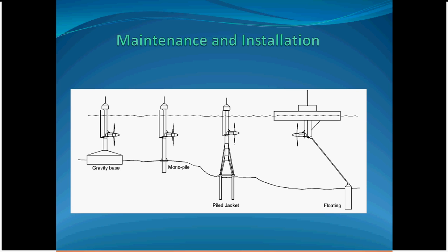The only drawback to this design, however, is in extreme weather conditions or in strong storms, forces can act upon the anchor, and this can cause problems with the turbine. So the best solution is to use either the monopile or the pile jacket. Now, both of these use steel towers that are actually drilled into the ground, typically about 4 meters.